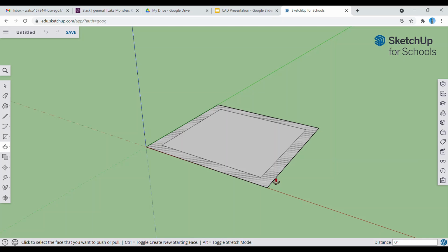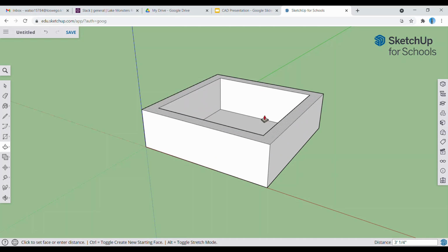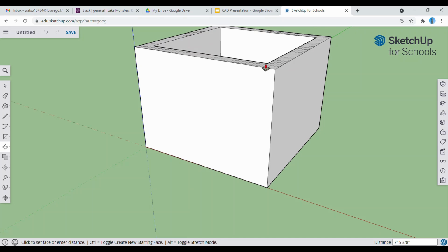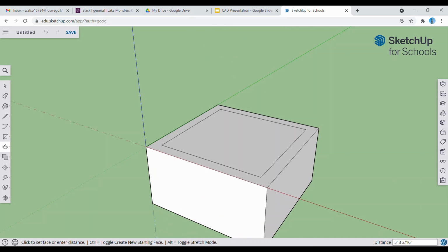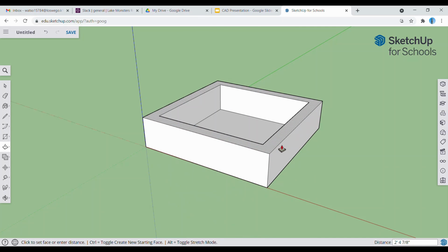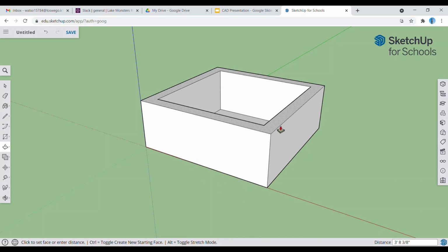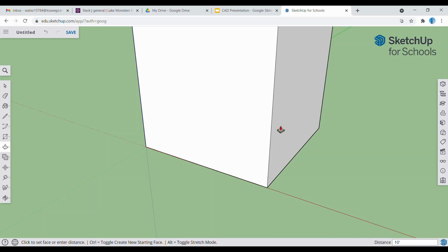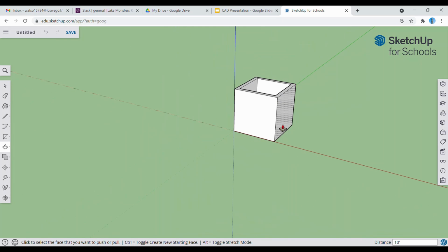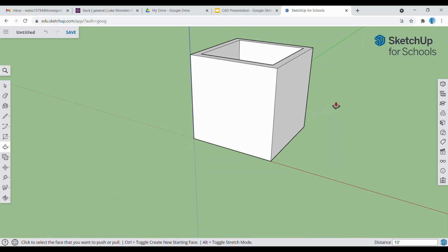The Push Pull tool works like an extrusion tool. As you can see, I can drag up and that'll bring the walls up to create a three-dimensional shape, or we could go down. In this case, we want to go up. Let's keep it the theme of 10, so 10 feet. Enter. But when we look at this and decide that that's too tall, well, we could either do it again, or...